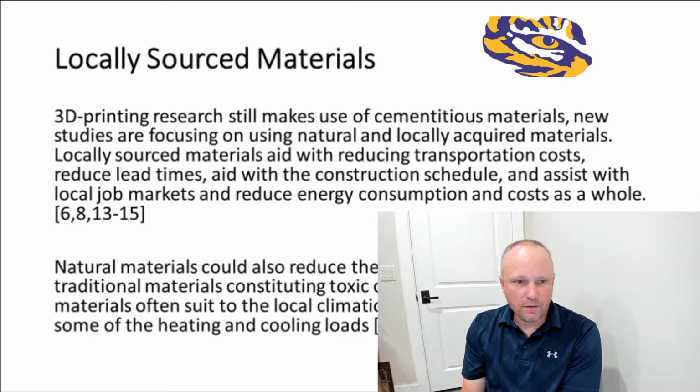3D printing research at scale makes use of cementitious materials. New studies are focusing on using natural and locally acquired materials. Locally sourced materials aid with reducing transportation costs, reduce lead times, aid with the construction schedule, assist with the local job markets, and reduce energy consumption and cost as a whole.